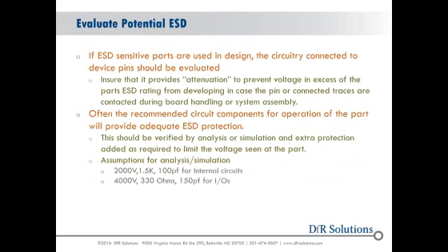If ESD-sensitive parts are used, then the circuitry connected to the device pins needs to be evaluated. Ensure that it provides attenuation to prevent voltage in excess of the part's ESD ratings, in case the pin or connected traces are contacted during board assembly or handling. Often the recommended circuit components for operation of the part will provide adequate ESD protection, and you need to verify them by either analysis or simulation or possibly testing, and we've provided some assumptions for that analysis here.